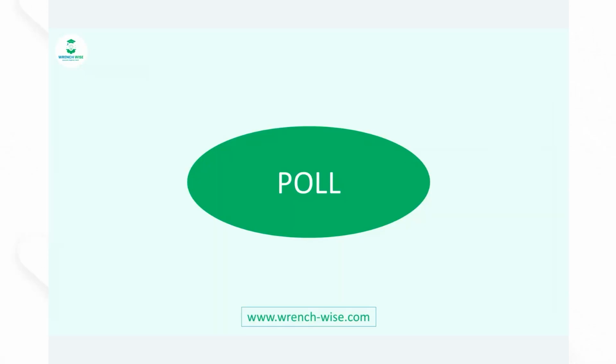Great. I have a final poll. When running the FVDOM model, you see heat radiating in distinct stripes or a starburst. What is the root cause here? The angular resolution is too low. So again, if the nPhi, nTheta settings are too low, the solver does not have enough discrete rays to cover the entire sphere. This results in this starburst effect where heat flux appears artificially striped or star shaped.